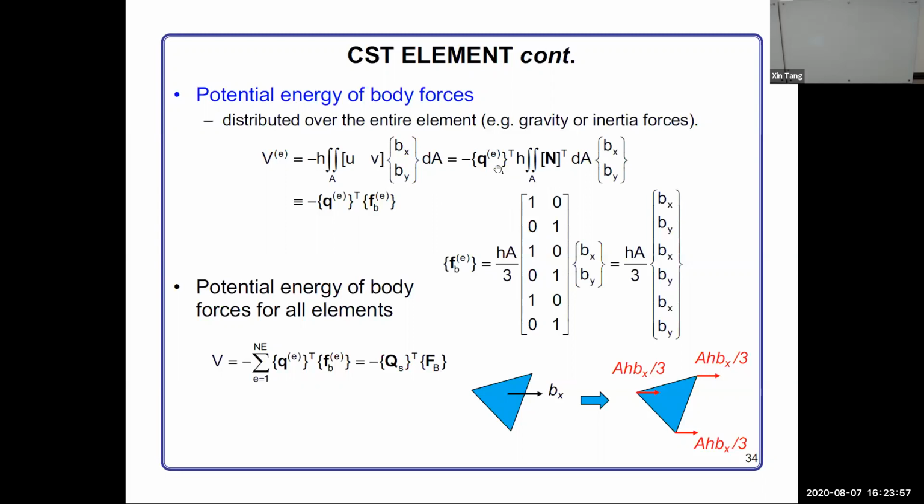And then the shape function matrix will remain inside the integral. This has the X and the Y. Then times the body force, and then times dA, okay? And then you have the thickness here. So eventually this will result in the degree of freedom times the body force terms. This body force term contains both the shape function, the volume information, as well as the normalized body force.